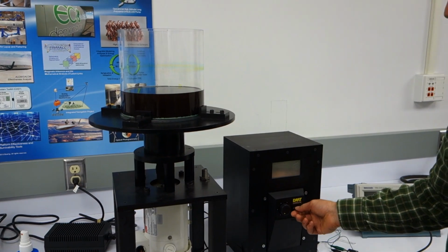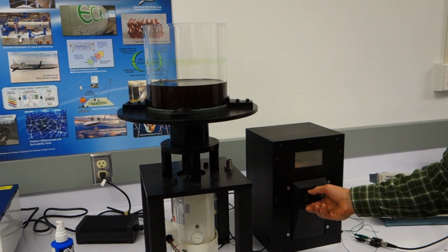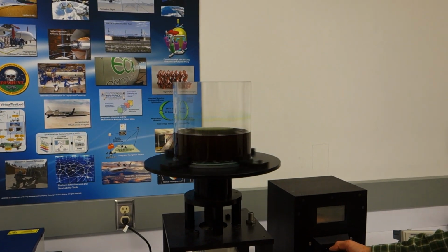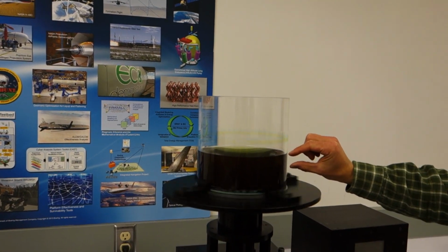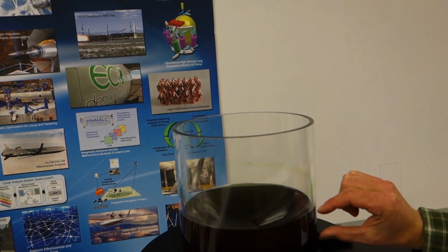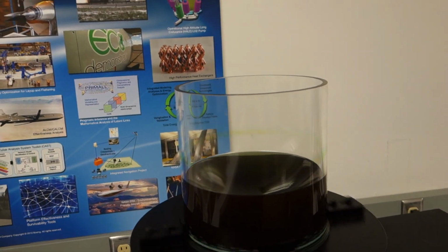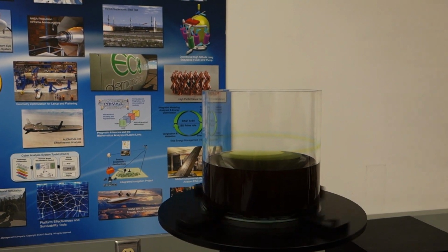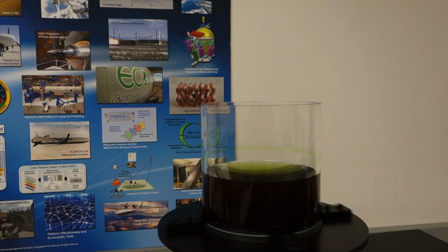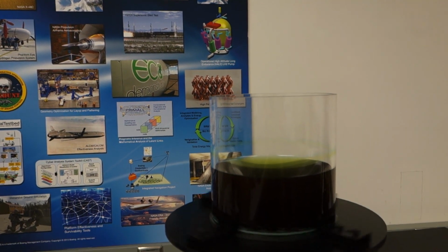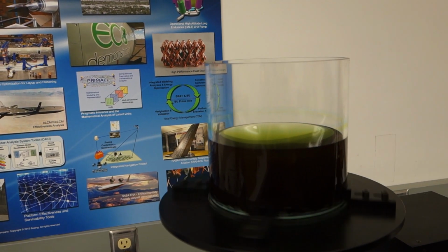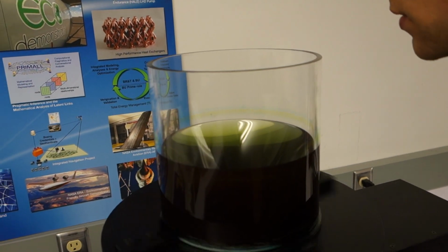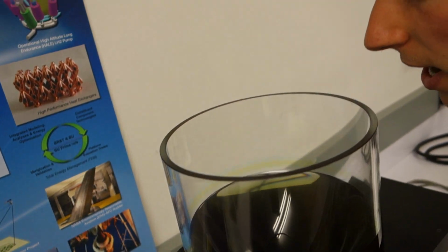Okay, so here we are. I'm going to spin it up, and just note that if I had taken note of that initial height and this new height, that would not be sufficient to know what the height z is as a function of capital R. What I will do is spin it up fast enough so that the bottom of the free surface, the vertex of my paraboloid, is just touching the bottom of the cylinder. So I'll go spin it up beyond that point.